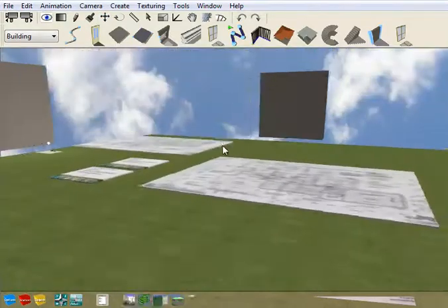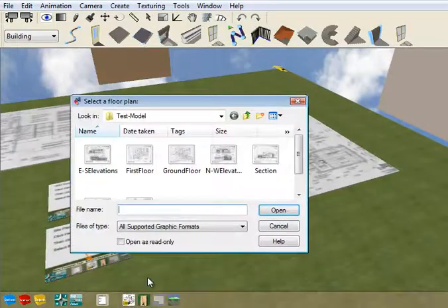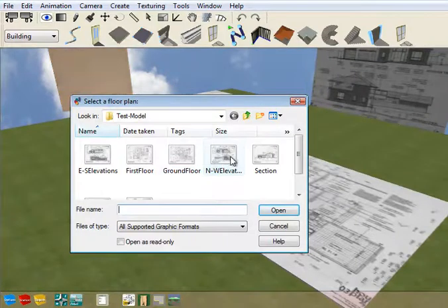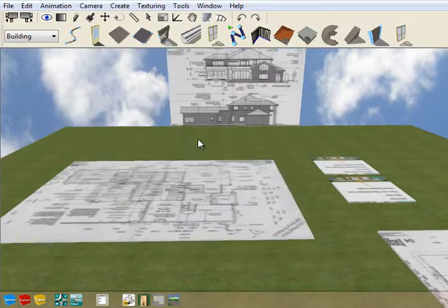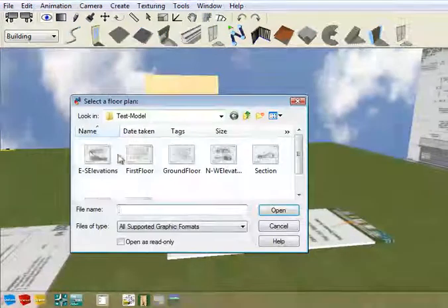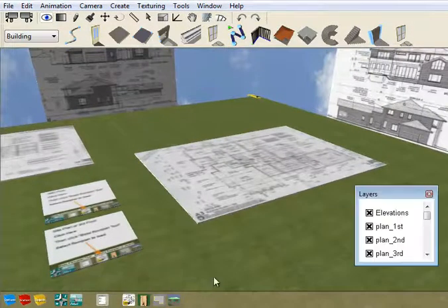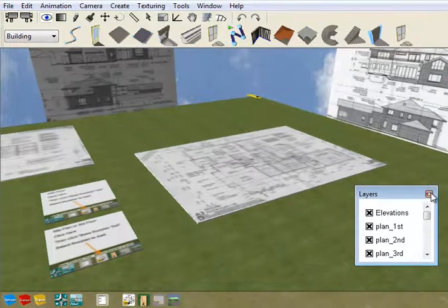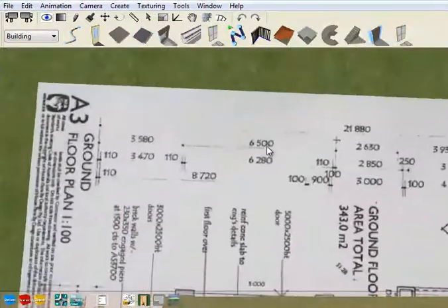Then what I'm going to do is locate the north arrow, and there it is there, and I'm going to click on that elevation base and load in the north elevation. Then I'm going to click on that one and load in the west, load in that one, load in the south, click on that one and load in the east. Now you can turn those elevations on and off by simply clicking the display presentation layers button and unchecking the elevations layer.